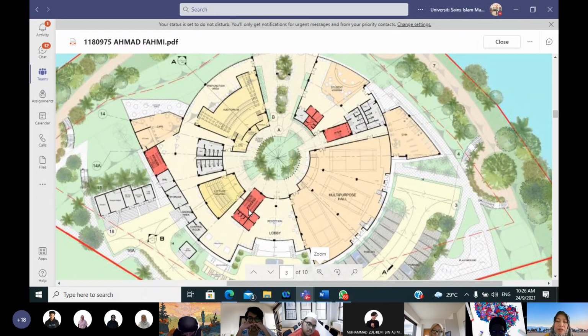If this building is going to be sprinklered, you have to identify sprinkler. If non-sprinklered, there is no sprinkler provided in this building, so every 45 meters there would be a staircase. Okay, boleh faham ke Hanan?